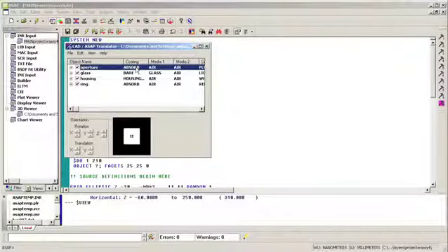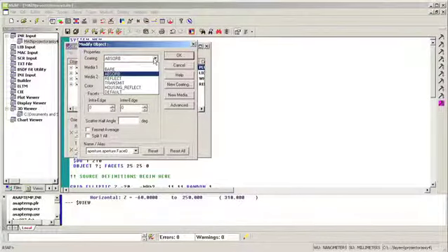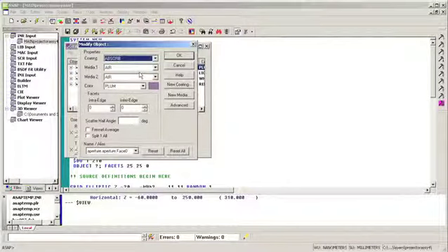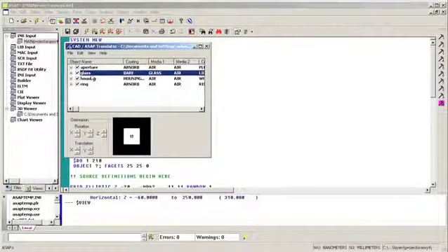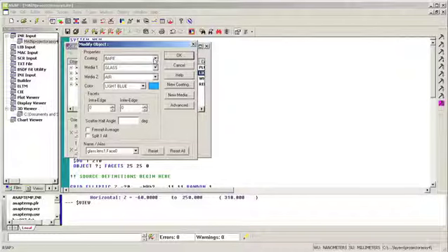So here, if I right-click, I can modify and put different coatings on different layers. So here I've got an absorb coating on my aperture because I don't want any light transmitting through it. I've got interface of air on each side. So I hit OK. And I do the same thing with the other layers. So here I've got a bare coating on for Fresnel reflections.